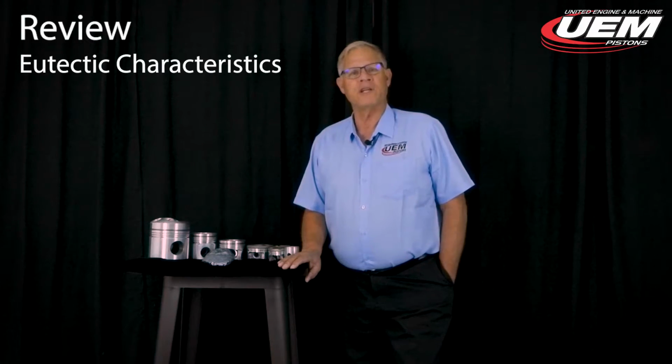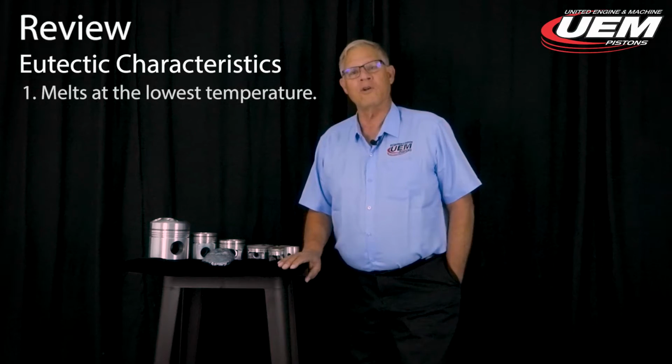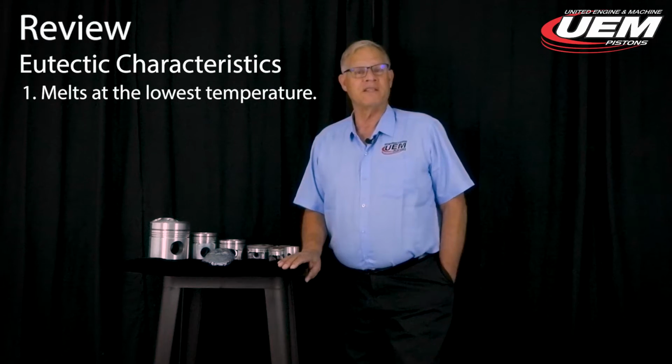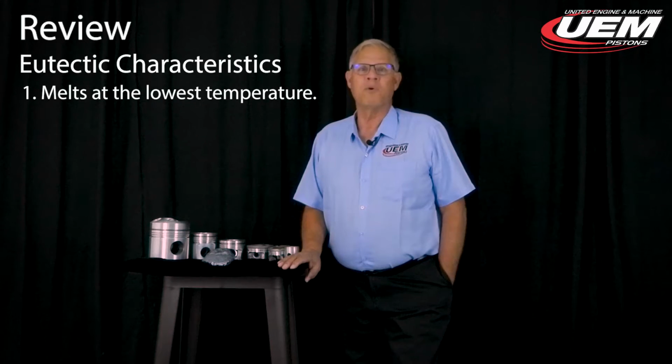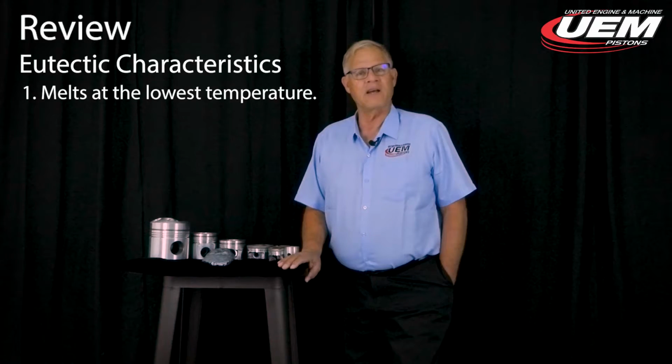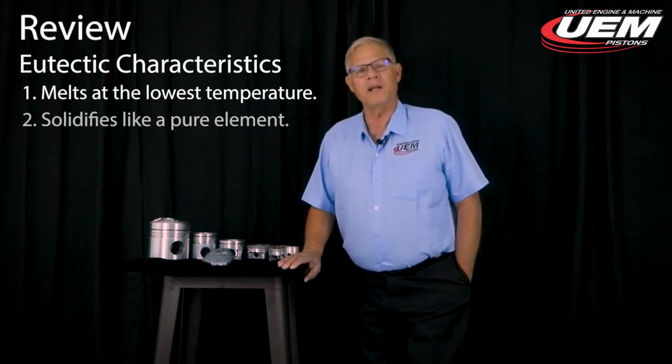The first major characteristic is that the alloy melts at a lower temperature than either of the constituents added. And that is probably the most important characteristic of a eutectic alloy. But the second is that it solidifies like a pure element.